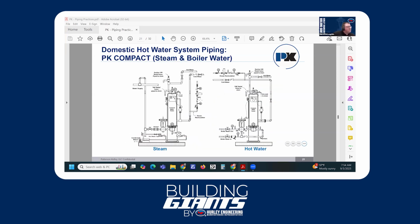Let me go one more. So this is just showing the hot water, and this is our shell and tube option often. So again, if we only have steam as a heating medium, or if we have non-condensing boilers, then we would go to this shell and tube to heat our water, so that we don't have to worry about return temps back to our non-condensing appliances.